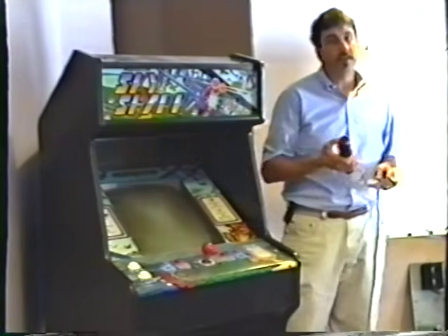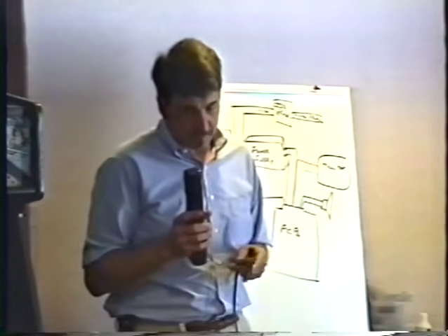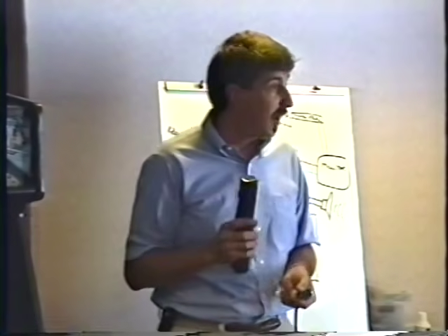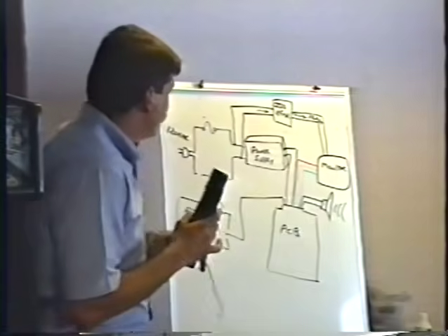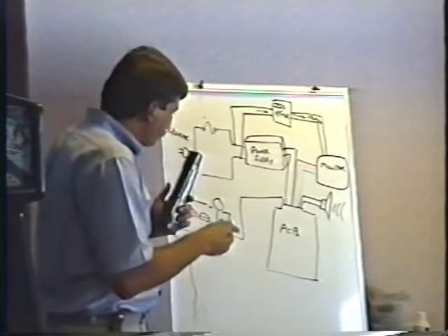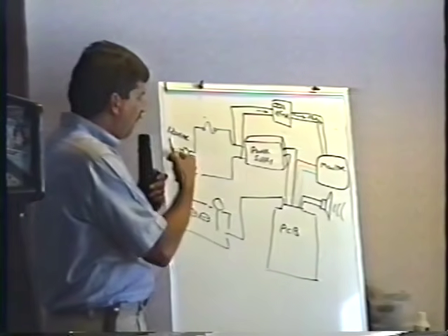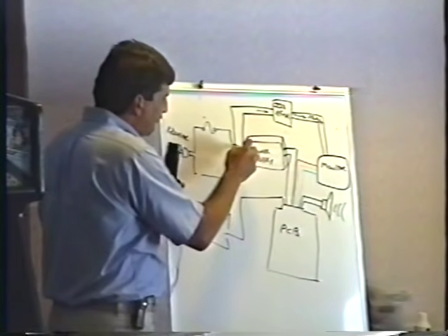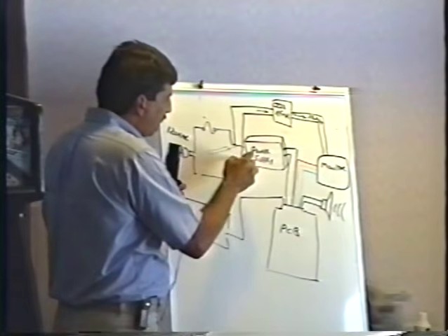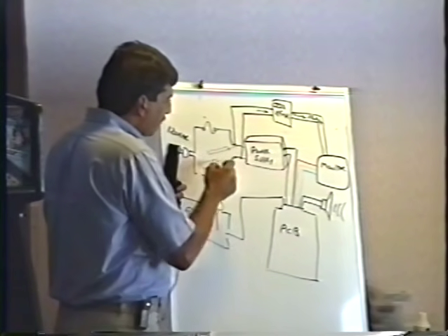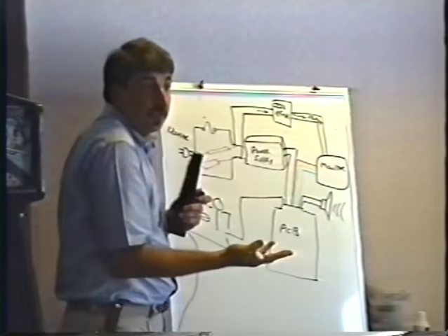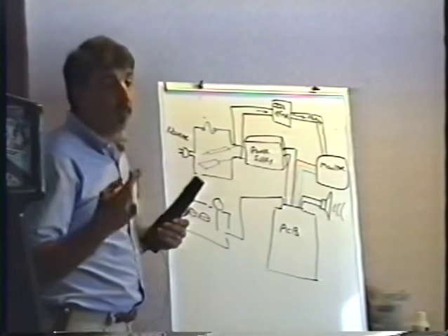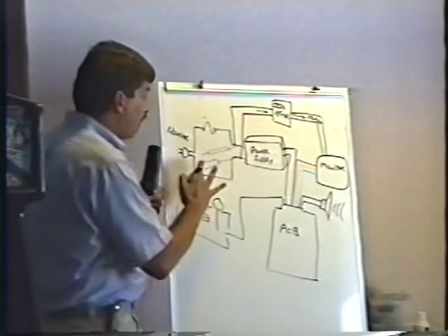If I have a choice of two different ways to troubleshoot something, with the power on or power off, I always do it with the power off. Here's what most people do to check this out. Most people will plug this into the wall, and with the meter set on 120 volts AC, they'll put their meter probes here and here and measure the voltage there. I mean, that's what most people do. You go, oh, well, there's no voltage there. That isn't how I do it, because there's a better way to do it with the power turned off.